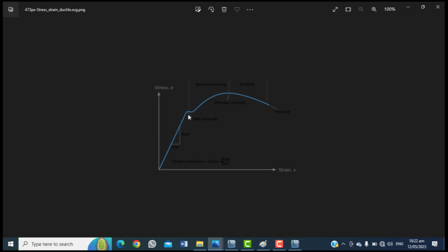So it means that for primary stress, yielding is forbidden. ASME B31.3 will also tell you that it is forbidden for yielding to occur due to primary stresses. So we do not want yielding to occur, because when yielding occurs, it means that the limit of the allowable stress has been exceeded, and most times it's just a fraction of your yield strength, right? So whenever I have an applied stress value that exceeds my yield strength, I'm going to have a primary stress failure because yielding has occurred.